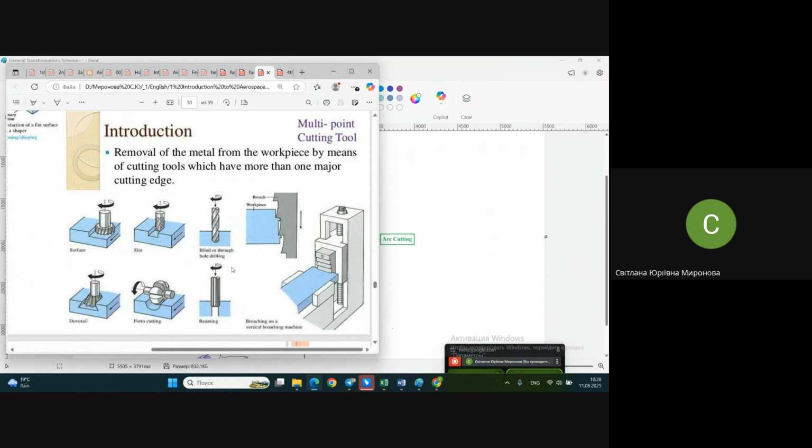What is next? I hope you understood from my tired explanation that the more blades, the better. Why is it better? Because you can afford to cut a thinner layer of material with each blade, and due to this you finally have higher quality and higher surface finish. So 2 blades in a drill is rough processing. 5, 7, 10 blades at the bottom of a countersinker is already better processing. And when it comes to a couple of dozen blades in a reamer, it's practically ideal processing.